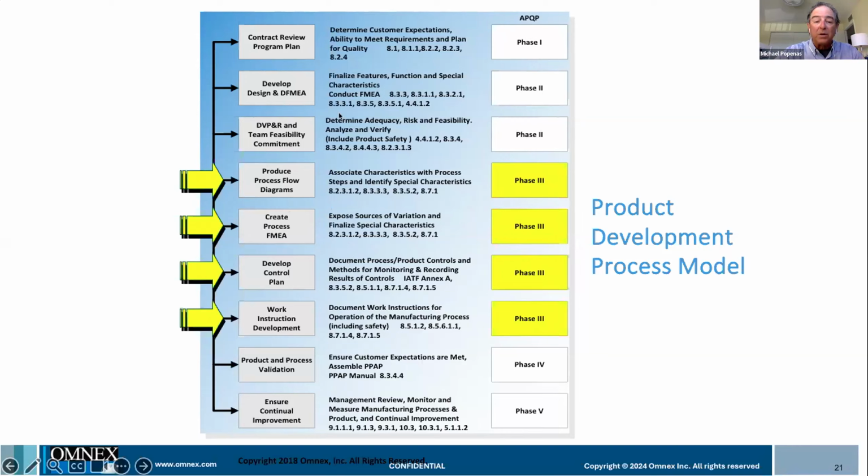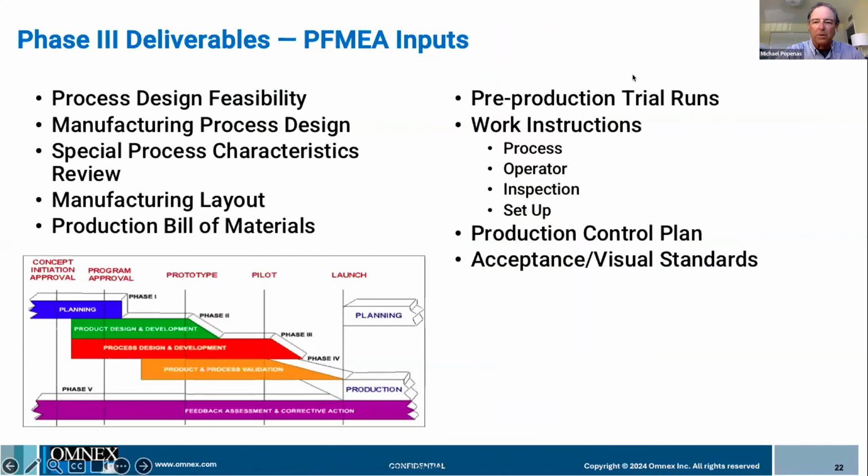Up early is where we start to say, hey, this is where we apply design for manufacturing and assembly to drive those RPN numbers down through design. Hugely important, because when we get to the stage of process FMEA, we're focused on how we hone in our manufacturing system to lock in those requirements so we have a production system that produces with fewer errors, driving off of those simplified designs.